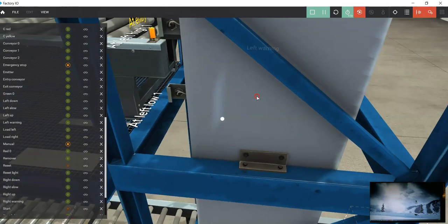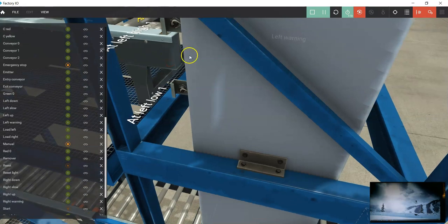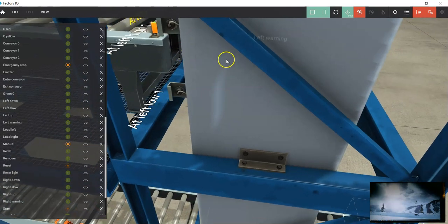These are two sensors here, and the elevator has to be positioned so that both of these triggers are on to say that we're at the proper level. We need both of those on so that the pallet makes a good smooth transfer from the elevator section to the conveyor section.